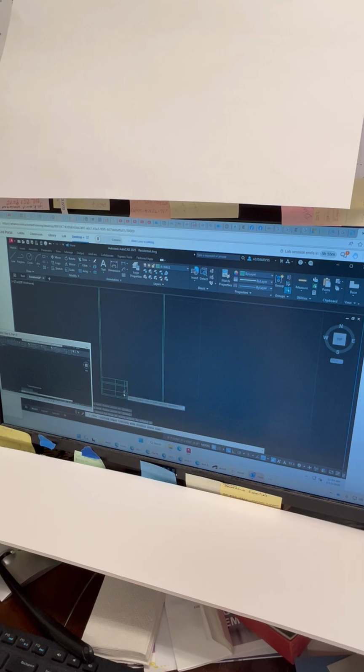There are various places throughout this plan where I'm going to need to use the geometry, and it's best if the lines are all one line. Now I've got several different separate lines, and if I offset, it's going to make things a little bit more complicated. So hold off on that urge to trim everything to fine detail until we get to that point.